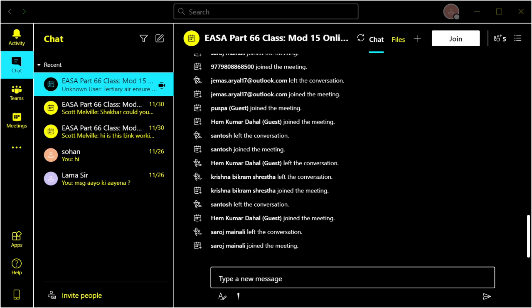You will get a new set of plugs from the stores, and they will be painted as well, because some engines might have 1 or 2, some engines might have 5: blue, reds, greens, whites, yellows, and that sort of thing. So make sure you put the same colour plug back into the same position when you place it. So do one at a time, take the green one out, you get a green plug, put the green one back in.